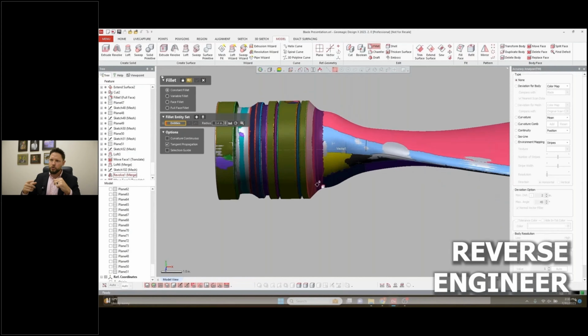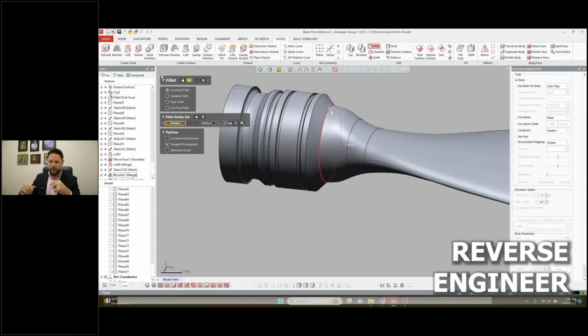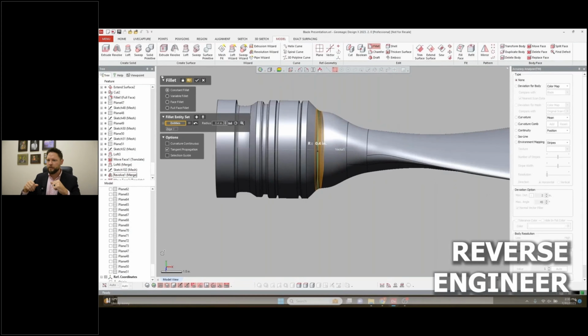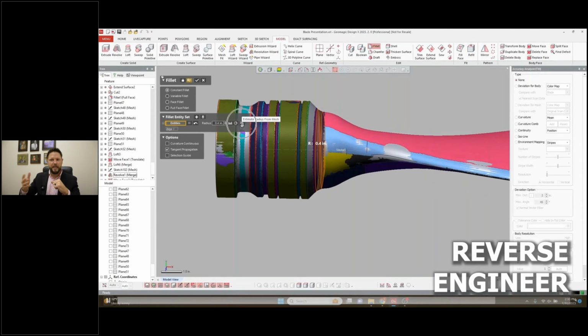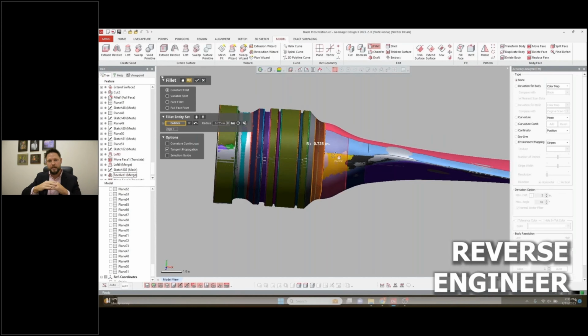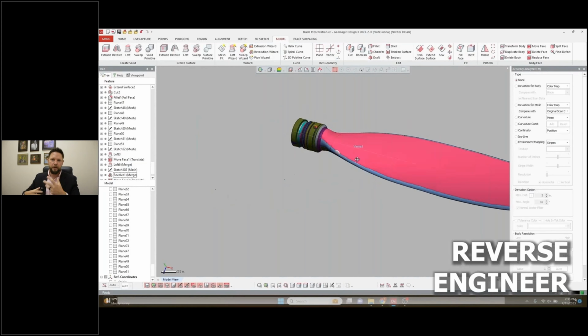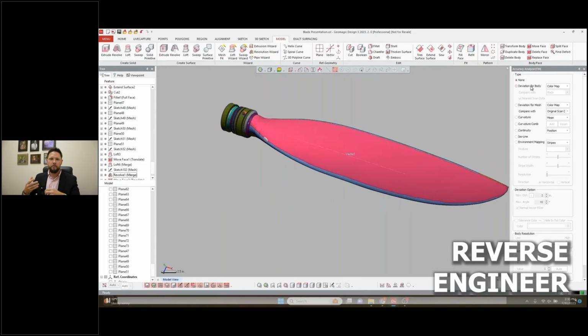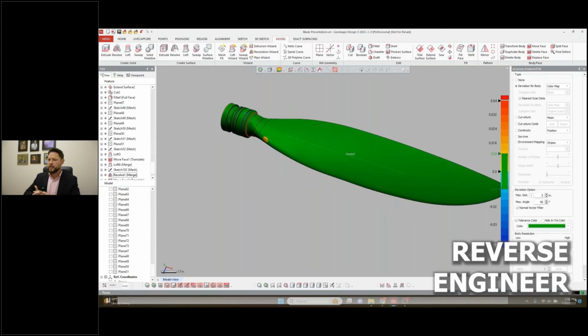And then the last tool, we got this fillet tool, and you click on it, you think, oh, that's cool. That's just a fillet tool. But we have this estimate radius for mesh button, which is awesome because it instantly will measure that corner and push it up to the mesh and give us what it thinks is that radius. And then we can fine tune that number from there and make it something, when we think about design intent, what it was most likely originally manufactured as.